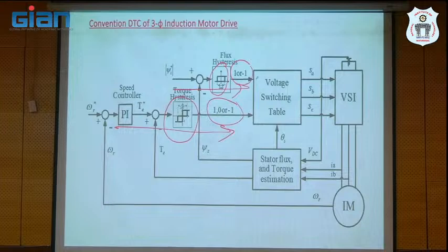Yes, if you take more states, the torque profile will improve. Our top priority in an electric drive, our primary objective, is torque control. By taking more levels, if you are able to concentrate on the torque profile effectively, what will happen? The performance of the torque will improve. Further, flux control is our secondary controlled variable.